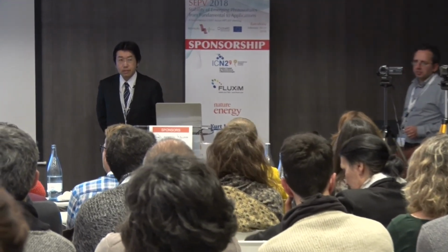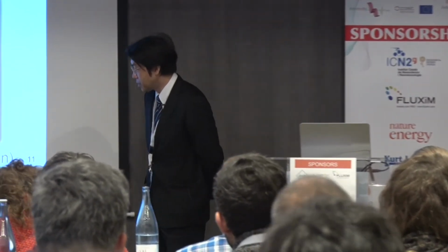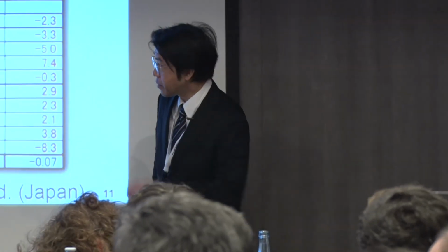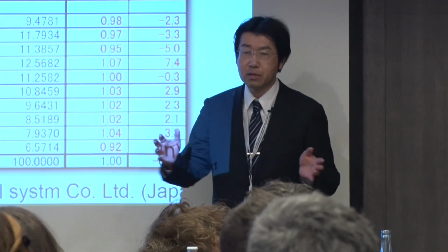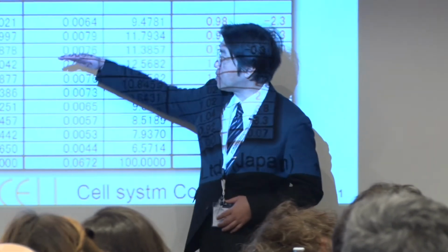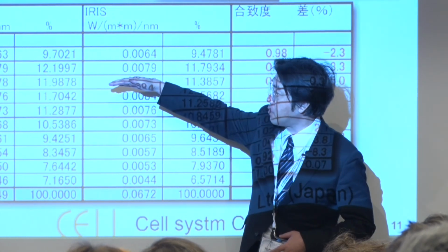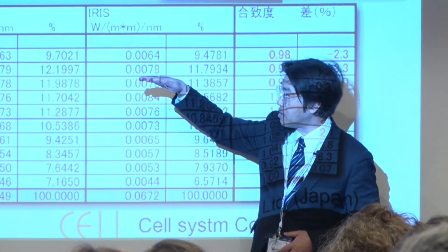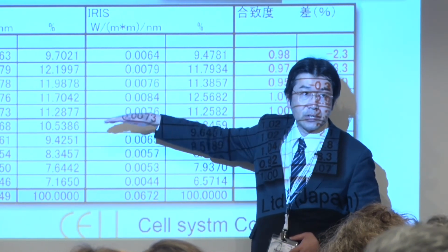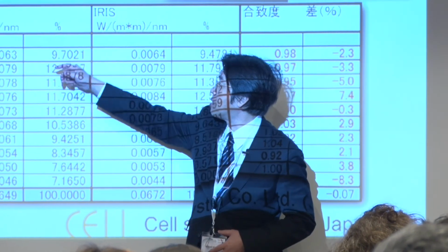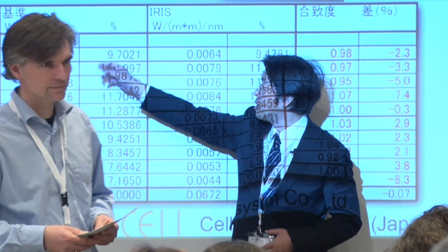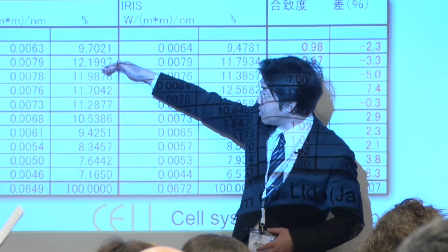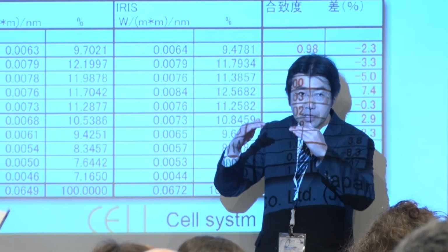Yeah, you are right. It absolutely depends on the shape of the spectra of the light source. In our case, the IEC committees have definitions with different 100 nanometer bands for each wavelength range. For air mass 1.5, each band has a given percentage, and we are keeping these ratios for each intensity.